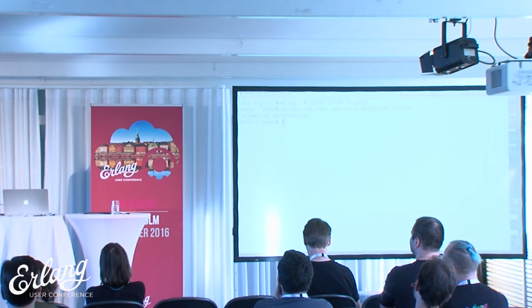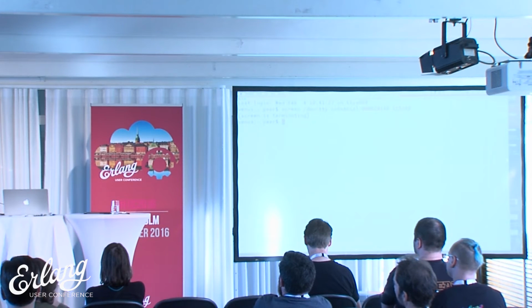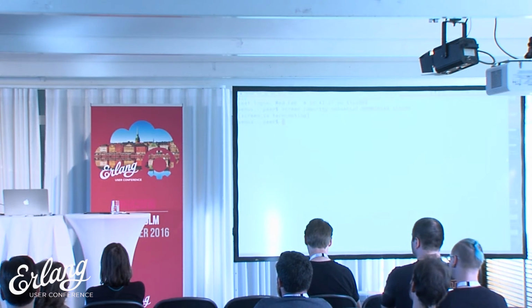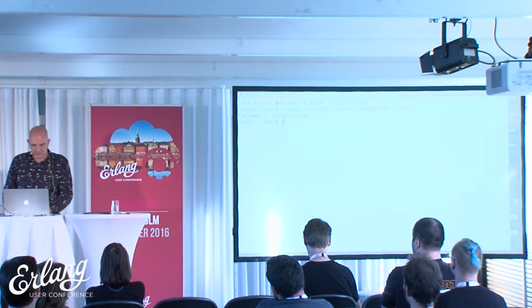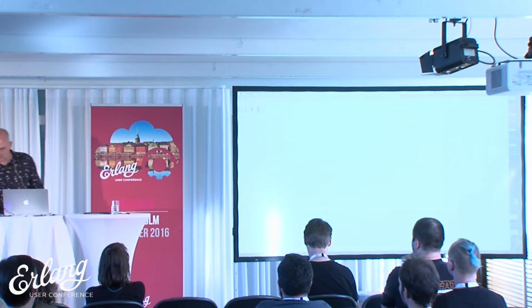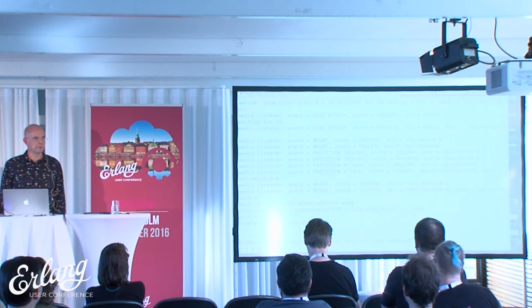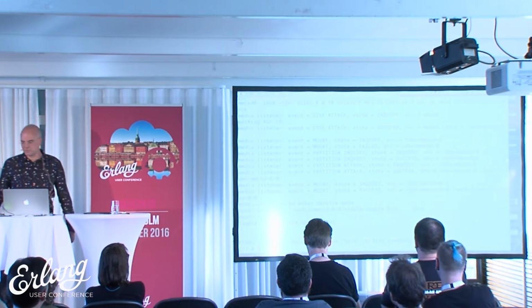And then you see something's going on with the thing, and this LED changes color. So this is not much to see, but what happened actually is that the bootloader booted the hardware. It actually read a little program that's not in Erlang yet, but it's in C, from the SD card. And the little program actually changes the bits on the 3 lines of the RGB LED. So in order to see a little bit more, let's look at the serial terminal. So yeah, it works. I reset it again so you can see the boot process. So that was all. It's booted. So 2 seconds. I do it again.